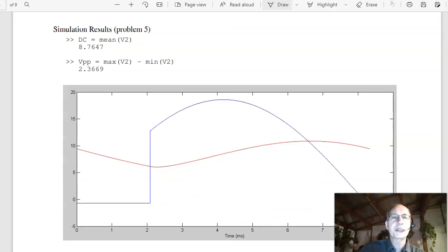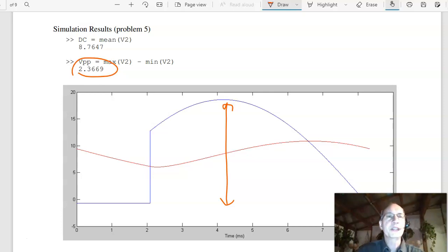It won't be exact because V2 right here is not a sine wave, so the first harmonic is not exactly 19.3 volts peak to peak. We're doing approximations. Likewise, what I calculate for V2 will be approximate. It's not too bad. Kind of my book is, if you want to get more accurate than these approximations, throw it in Circuit Lab.